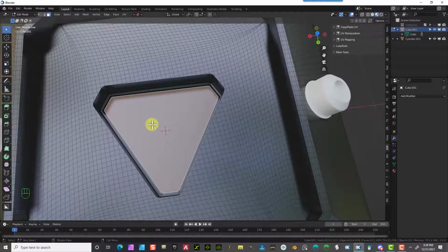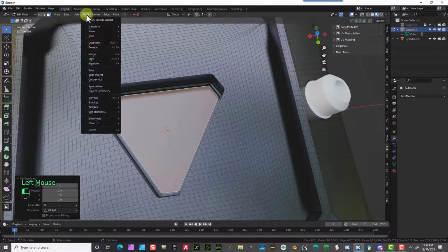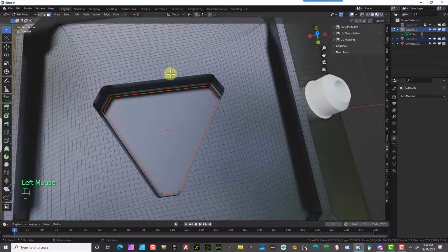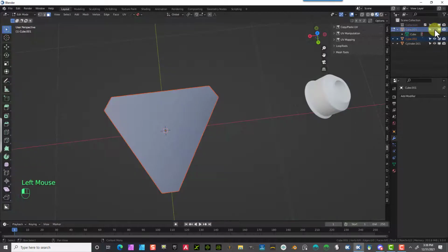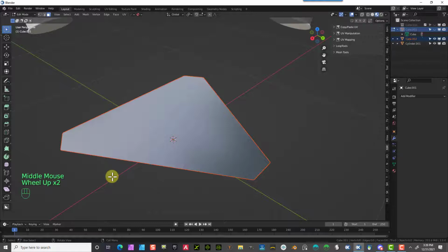So now I've got the polygon selected still. I'm going to hit Shift D, so that it separates it as a separate poly. Okay, now I'm going to the mesh section and separate this part out as a separate object, so it becomes its own. And once I've done that, I'm going to go in there and modify. I'm basically going to just delete the face itself, not the edge. I'm going to use the edge to actually create a curve, so I can add some thickness to it.